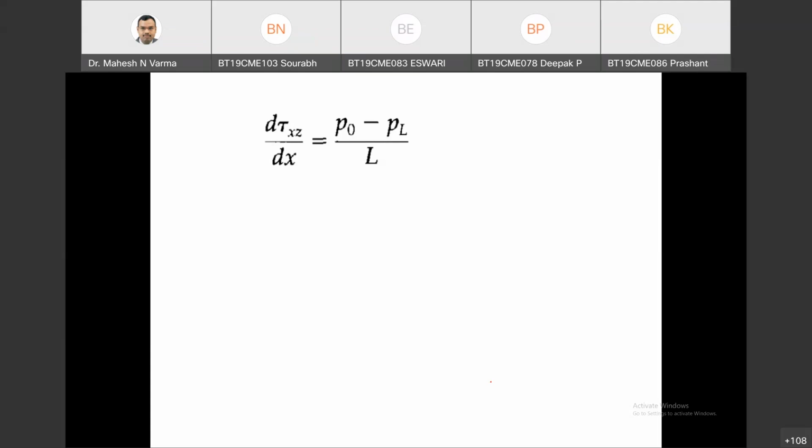Why is gravitational force not in the picture? Here the pressure is just a pressure given by external agencies like a pump. So this pressure gradient is created by an external agency. Gravitational force is neither supporting the flow nor opposing the flow.